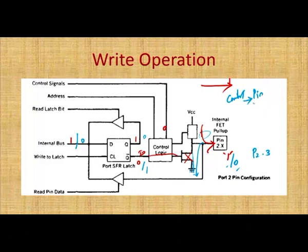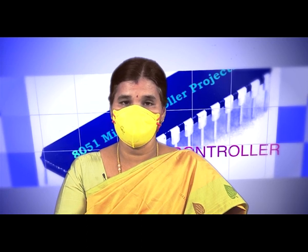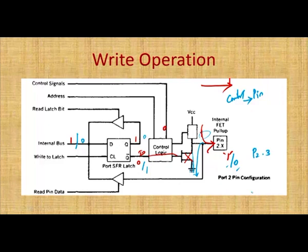So, the write operation means from the data line to the external pin we are sending the signals. Sending the signals means writing operation from the data line to any one of the pins, or you can consider the data signals which are connected with the LEDs, right. If you are giving the value 1, the LED will be on, if you are giving the value 0, the LED will be off. So, in this pin you connect one of the LEDs, then you will get a clear understanding of what kind of signal you are passing.